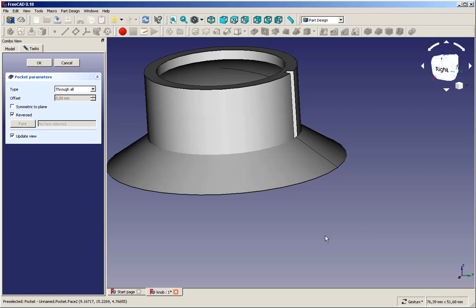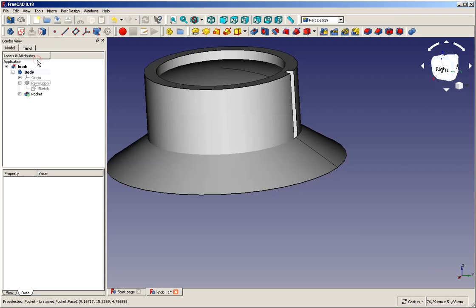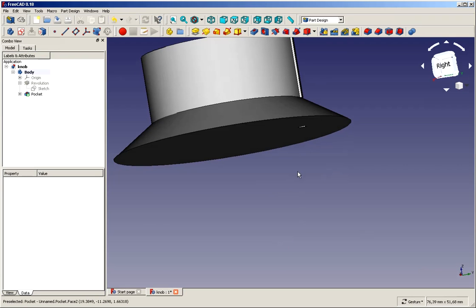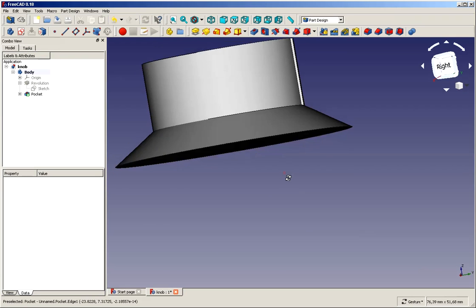It would not make a lot of sense in this construction because there's only this line on that height. It's not needed that anything else is on this height, so it would be a little bit shooting at the bird with the cannon. So the better way is, in this case, we just create an offset for this sketch.